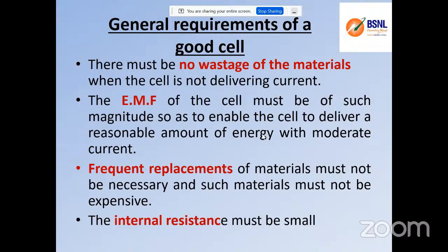And the same for internal resistance. It should not have much higher internal resistance, or otherwise the consumption of the load will be more within the internal resistance itself, so there will be more losses.